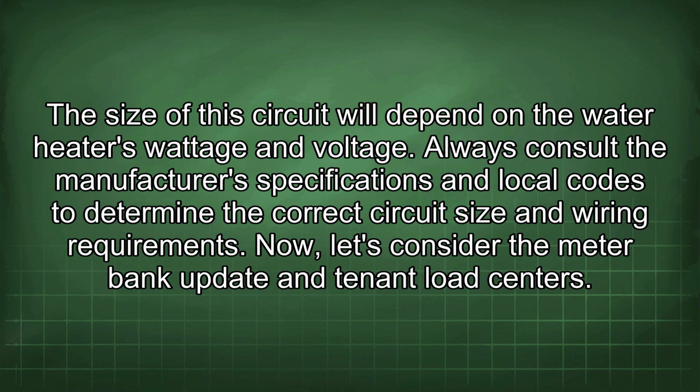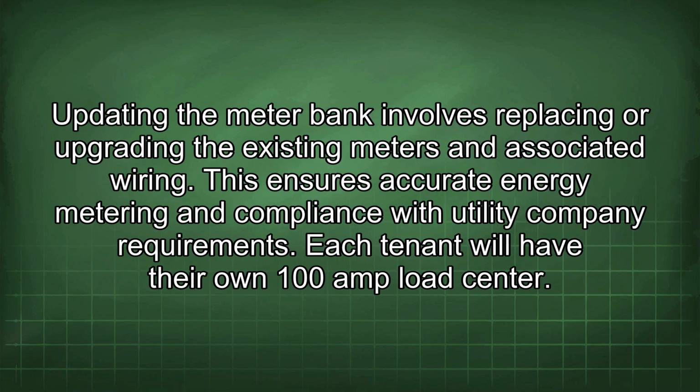Now let's consider the meter bank update and tenant load centers. Updating the meter bank involves replacing or upgrading the existing meters and associated wiring. This ensures accurate energy metering and compliance with utility company requirements. Each tenant will have their own 100 amp load center.